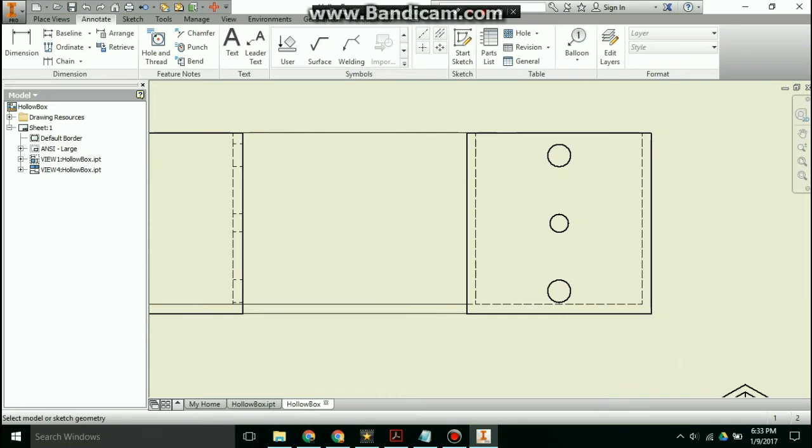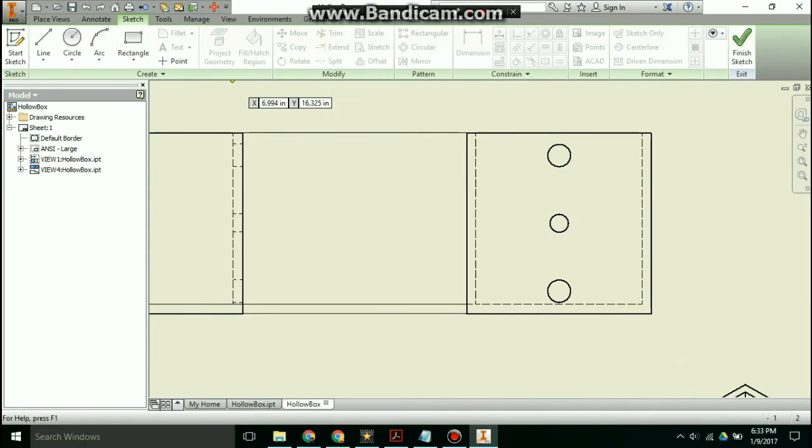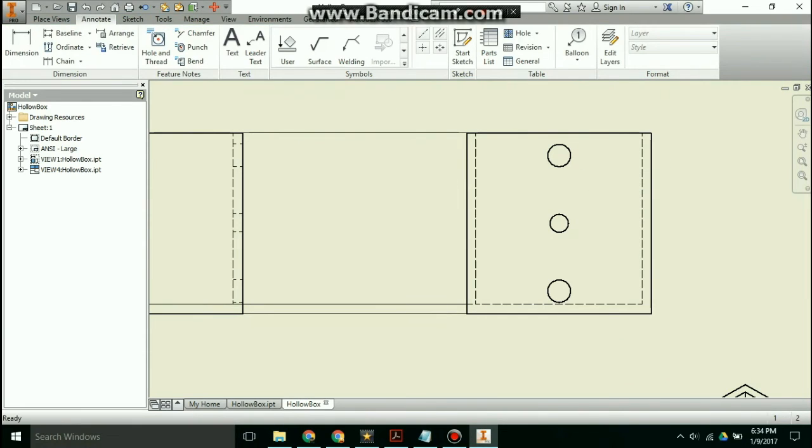Now, dimensioning circles is a little bit trickier, but shouldn't be hard. So what you want to start with is dimensioning all the way through each of these circles. That way you don't have to dimension each one by one. By showing that it goes through each of the centers, you show that each circle is 1 inch from the side. A better way of showing the centers is clicking this tool on the top, the center mark, and then clicking on each circle center.